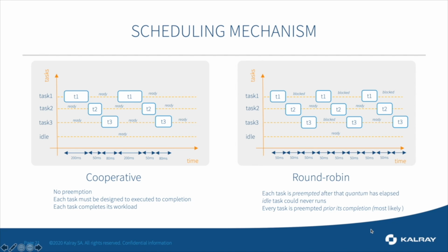Then, at the end, the scheduler will give control to task 2, which will do the same: start and run until its completion, then task 3, and back to task 1. You are ordering your tasks to be sequential and to give back the resource, the execution capability, to the next task as defined by your system configuration.